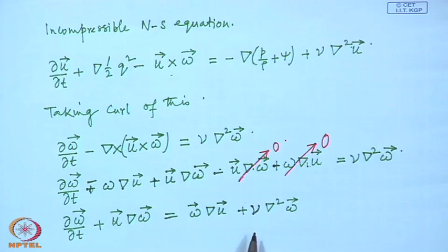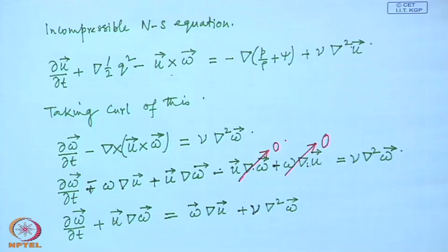See, this is also the Navier-Stokes equation. The Navier-Stokes equation written in terms of u is the same equation. This is not a separate or new equation, it is only an alternative form of the Navier-Stokes equation written in terms of vorticity as the primary or independent unknown. In many cases later on you will find that this form is perhaps more useful for practical use. An equation expressed in this form is called the vorticity transport equation.